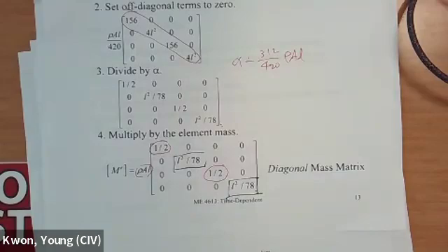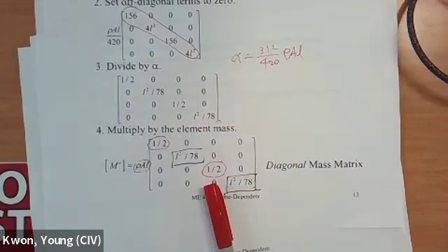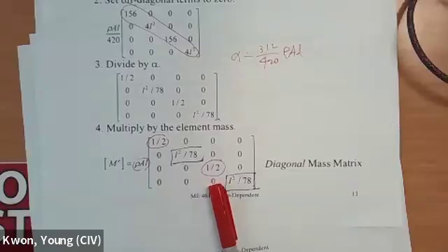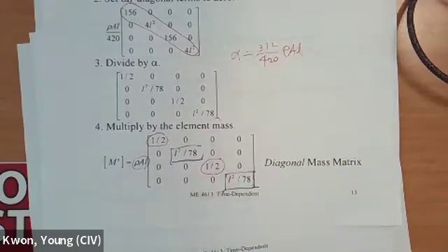So if you do the explicit technique, the consistent mass matrix is mostly the common one otherwise. But when you do explicit, the diagonal mass matrix is going to be the most common, so that you don't have to invert the mass matrix itself, because it is very straightforward.